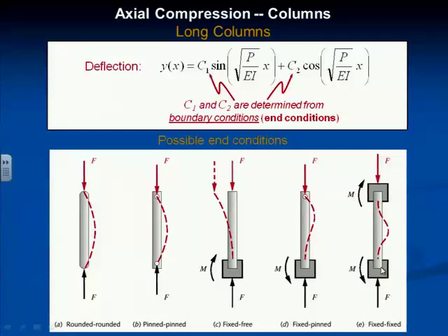So here's my rounded case. I could do pinned. I could do fixed, bury it in the ground. This is your flagpole, right? Free at the top. I could do fixed and guide the pin at the top, or fixed. And there's some other possibilities. I could guide the top and fix the bottom, and so forth.